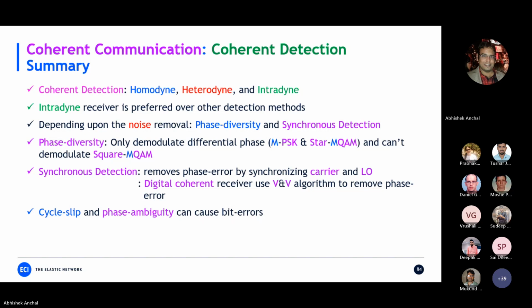Abhishek, I had two questions. One was, in Acacia, we have some settings for spectral pre-emphasis at the TX direction. How does that affect the filter design or recovery of the signal? Another question was, we can change the optical sensitivity of the transceiver using power limited and noise limited mode. Does that change the way local oscillator recovery is done, or how do we tweak the sensitivity of the receiver in these cases?